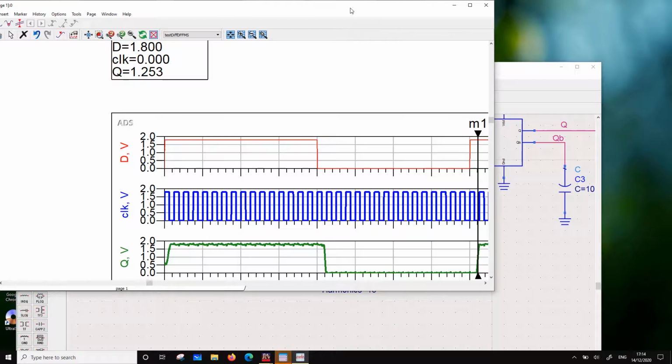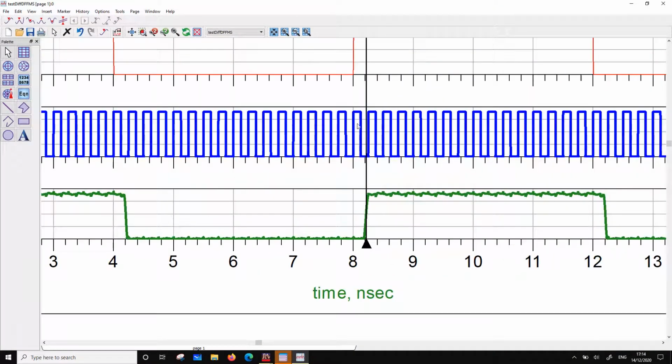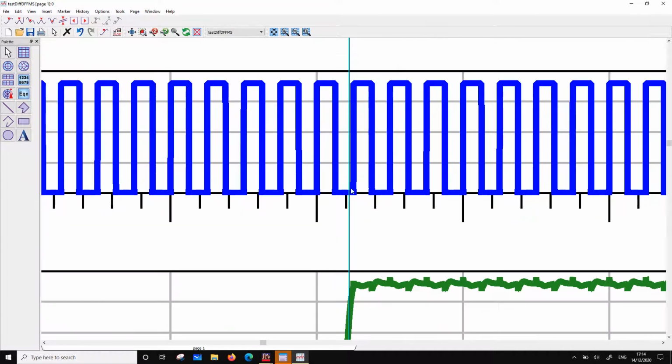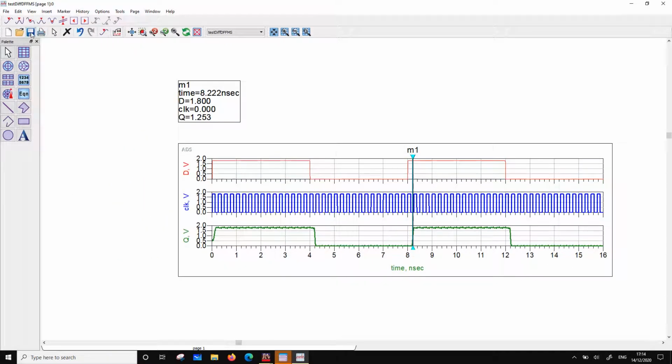But what margin did I get over here? Did I get any margin over here as a setup? Slight. Is that enough? No, it's not enough. It has to be a transition on the falling edge, right? Okay, so you understood the concept of critical path and maximum frequency of operation. Stuff like that would happen because of this.